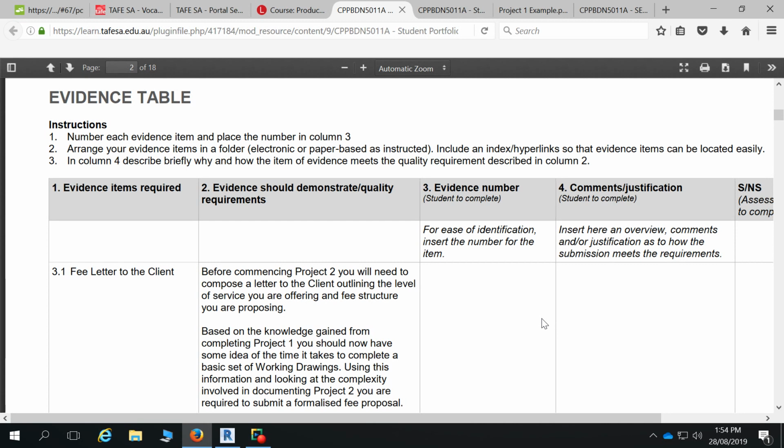So what you'll notice if you start looking around at Hebel buildings is you'll see just some compressed sheeting, like blue board and that sort of thing, and that's what you'll put in those areas. So they'll put some extra insulation in the back, but the difference in thickness of material between something like a compressed sheet and a Hebel panel is quite a lot. So then you've got to work out, how am I going to pack that up? What am I going to do? How's it going to be coated and all those sorts of things? So we'll have those sort of things to work around as well.